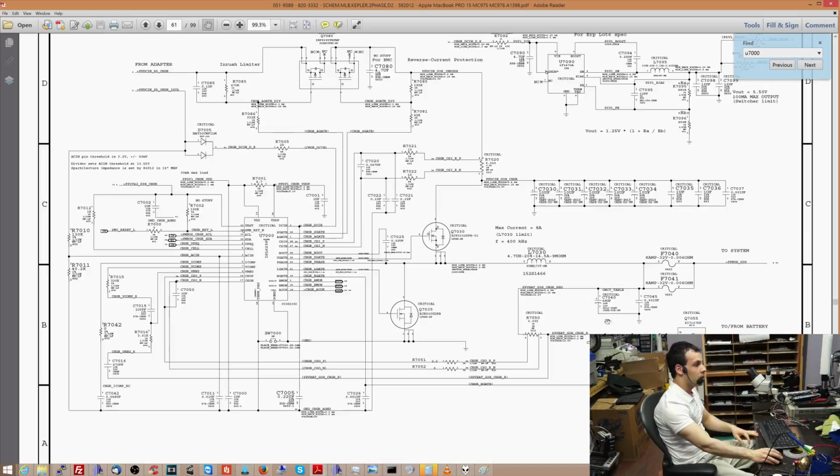So capacitors are always attached to ground on one end. Now, a very common problem is the capacitor dies, or that insulator blows, or it gets destroyed, and now the capacitor is shorted to ground. So the signal is shorting to ground through the capacitor.